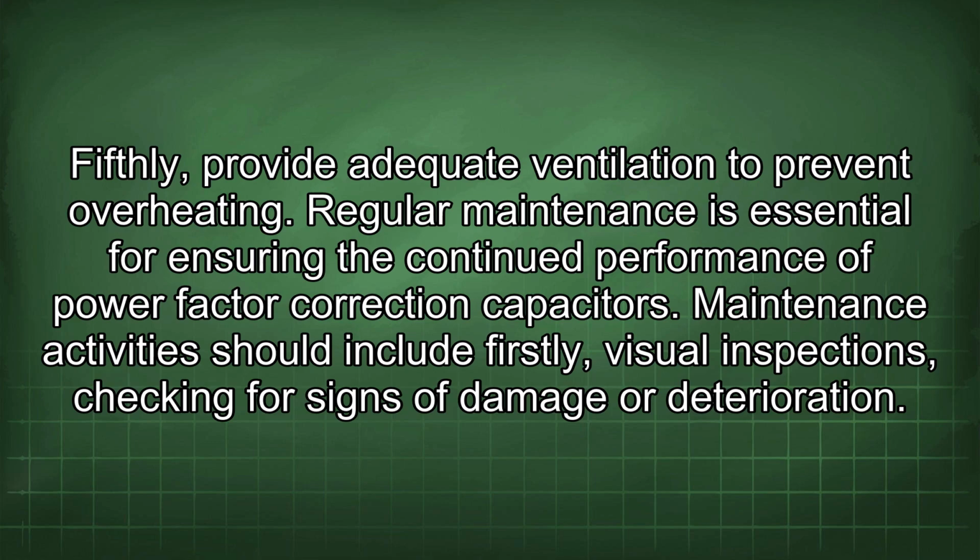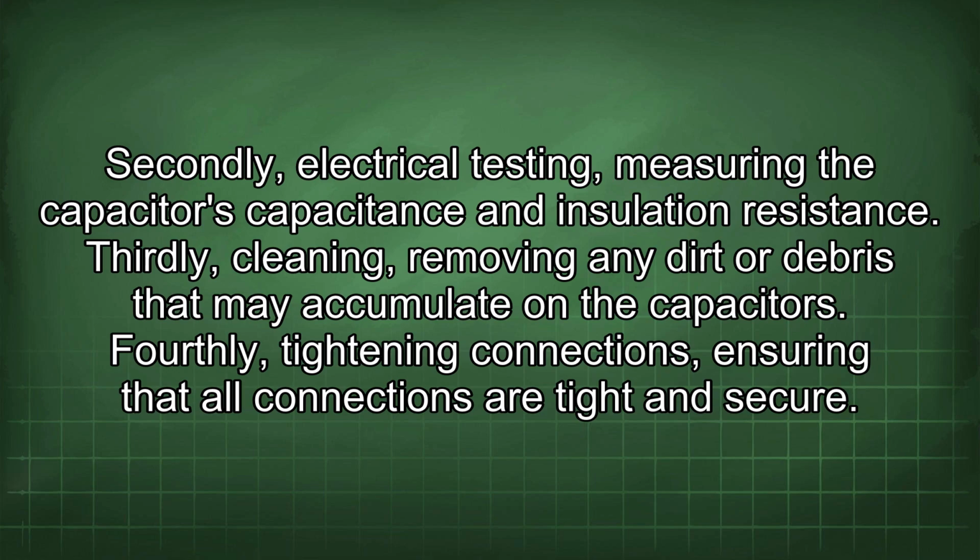Regular maintenance is essential for ensuring the continued performance of power factor correction capacitors. Maintenance activities should include, firstly, visual inspections, checking for signs of damage or deterioration. Secondly, electrical testing, measuring the capacitor's capacitance and insulation resistance. Thirdly, cleaning, removing any dirt or debris that may accumulate on the capacitors.